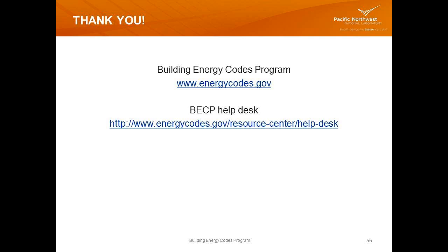Otherwise, it's the IECC's way of making sure that fenestration doesn't get a pass, if you will, or get considered too leniently through the total UA. And again, it would depend on what code we're talking about, and I'm assuming it's the IECC 2015 because that's the only one that prescriptively mandates fenestration requirements.